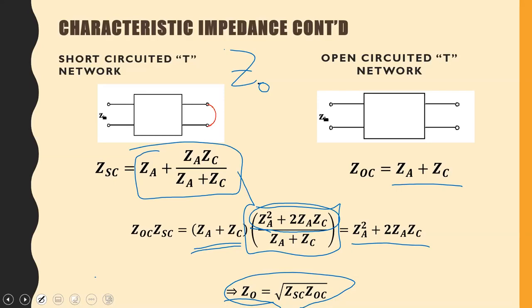You're not taking notes. I said the iterative impedance is the impedance which, when you connect it to the output of the circuit, results in the same input impedance. That's the definition. Hold on, I'm going back to iterative. I said the iterative impedance is the impedance that at the output yields the same input impedance.